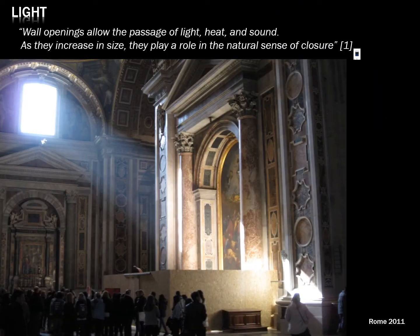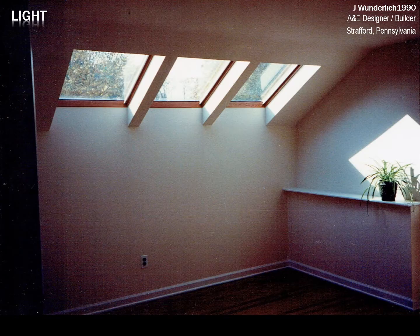I took this picture in the Vatican, in the cathedral, and you can see how that light is playing a role in defining the space. Some skylights that I designed in a house, you can get a feel for the light, how that's helping define that space. It's very dark in this room in the corner without any light on that side. This is the southern wall, and I had to put operable blinds because of that. Typically, you don't want to put skylights on the southern side, but it really needed light in here.